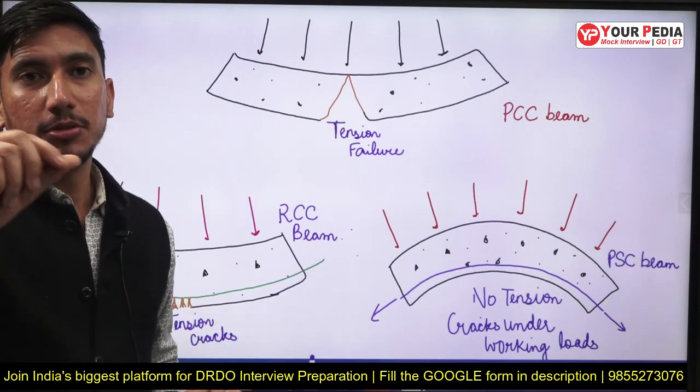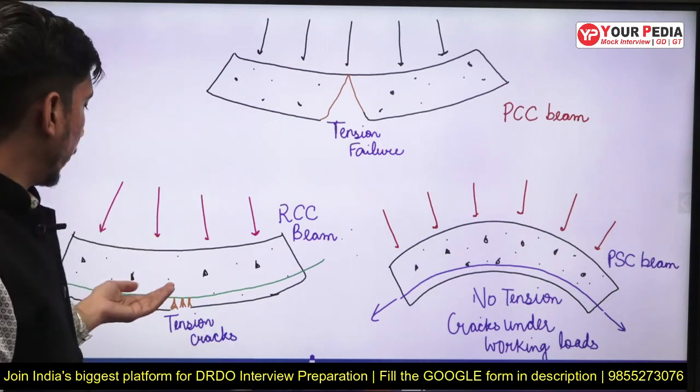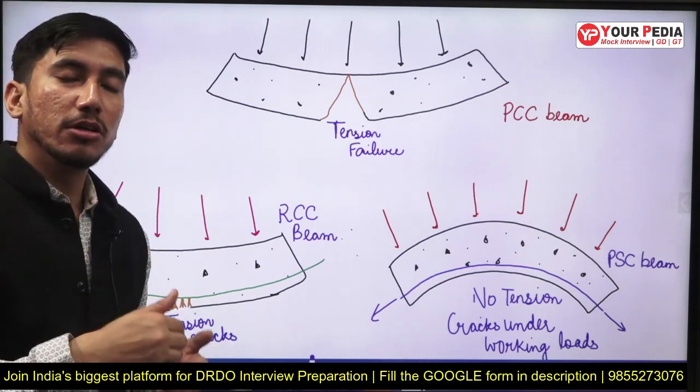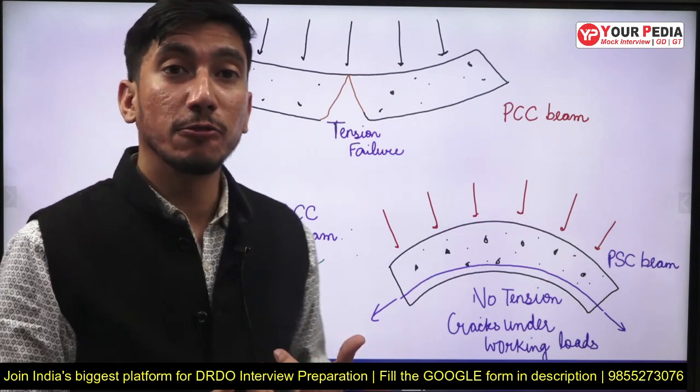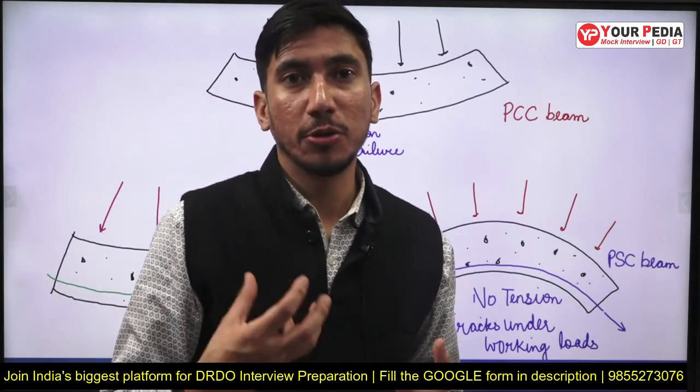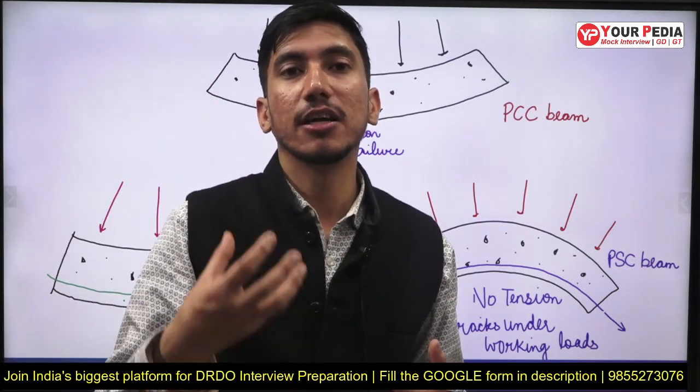When they reach over here, the tension will now be taken by the reinforcement, and these cracks will not propagate further, and the tension failure is avoided.